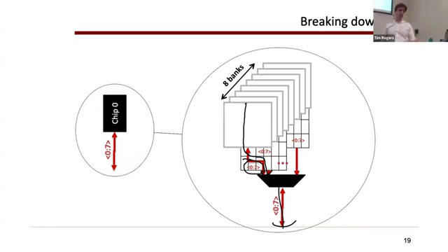And you may be asking, who decides where all this gets placed? This is the job of the memory controller and the physical address mapping, okay? And it's usually fixed because you don't want to screw with this. You don't want to move it around while the thing is moving. They have to move data around. It's kind of a huge pain. So there's usually modulo or some kind of index-based mapping, which we'll talk about later.